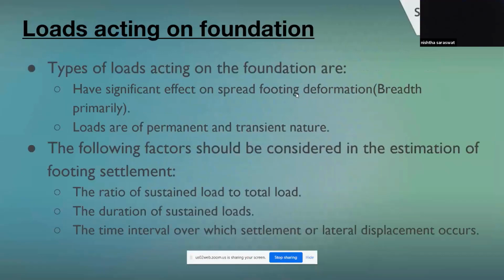Yeah. So coming on to the basics, for example, if I'm given the assignment of designing a foundation, the various components that I should need to design would be, first, understanding of the loads, which comes from the type of structure or the input that you will get from the structural engineer. The second one being the necessary soil parameters that typically a geotechnical engineer or a geotechnical investigation report will share with you, which is the cohesion, the friction, and the other values.